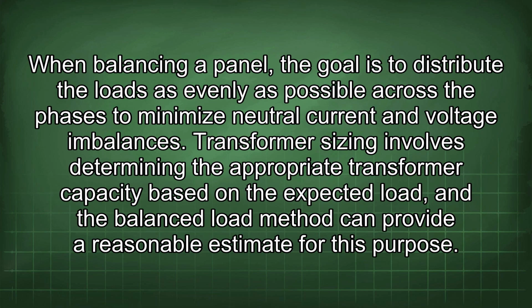When balancing a panel, the goal is to distribute the loads as evenly as possible across the phases to minimize neutral current and voltage imbalances. Transformer sizing involves determining the appropriate transformer capacity based on the expected load, and the balanced load method can provide a reasonable estimate for this purpose.